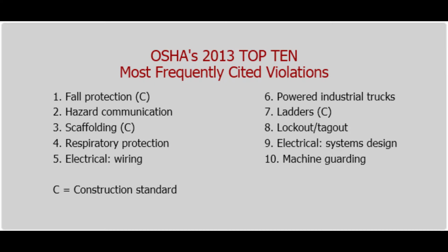Through a competent person, management will determine if the walking working surfaces on which its employees are to work have the strength and structural integrity to support employees safely. Employees are allowed to work on those surfaces only when the surfaces have the requisite strength and structural integrity as determined by the competent person.